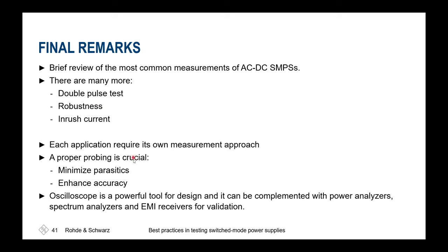And then you could also do an estimate already inside these test systems on the losses effectively and also the system behavior. In general, the parasitics are causing us the most headaches, and the higher the frequencies get, the more harmful are these parasitic effects. And that's also something we'll take care of in the presentation of next week, how our measurement system is affected by these high frequency components and also how to get a good accuracy or at least a reproducible measurement out of our setup.